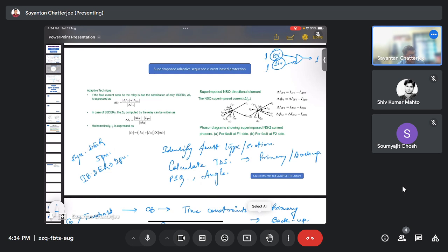So after that we'll have the rule base. Accordingly, the two decisions from the overcurrent and directional would go into the AND gate, and based on that output, that side relay would trip, means the decision is finally given, and accordingly the relays would operate. So the setting value, means the time of operation the relays should be operating, we'll have to find out, and the set point value would be from 0.3 to 0.5, and within this time they are operating.